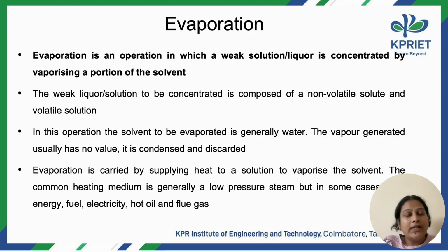So what I do is I supply some amount of heat to this solution to remove this excess solvent from the solution. So what happens? Any weak liquid that I have will be converted into a concentrated liquor. So this is the basic principle behind this evaporation operation.